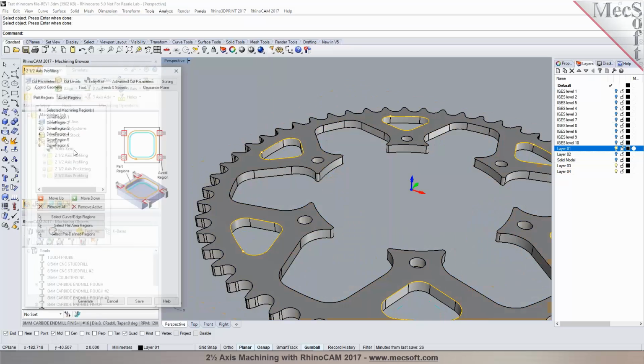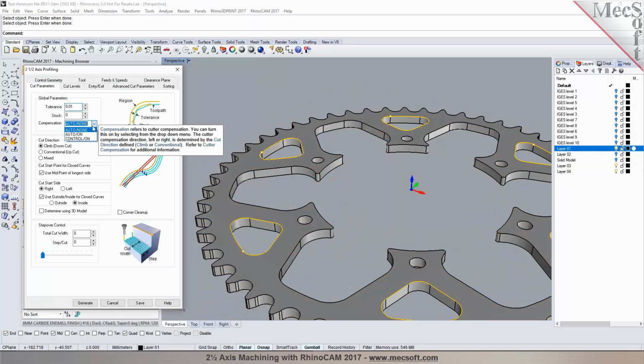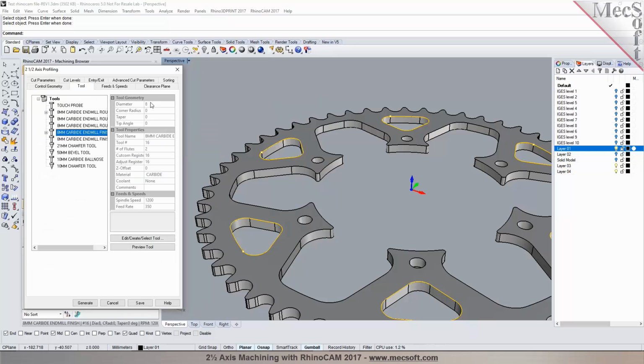When you use cutter compensation in here, we have auto on, which means the toolpath is still being compensated by the tool that you defined in here, so it's automatically compensated. So what you're compensating on the control is more like a tool wear. If the cutter is worn out and it's 7.8 millimeters as opposed to 8 millimeters, right? Yeah. You'd be compensating for the 0.2 millimeter.